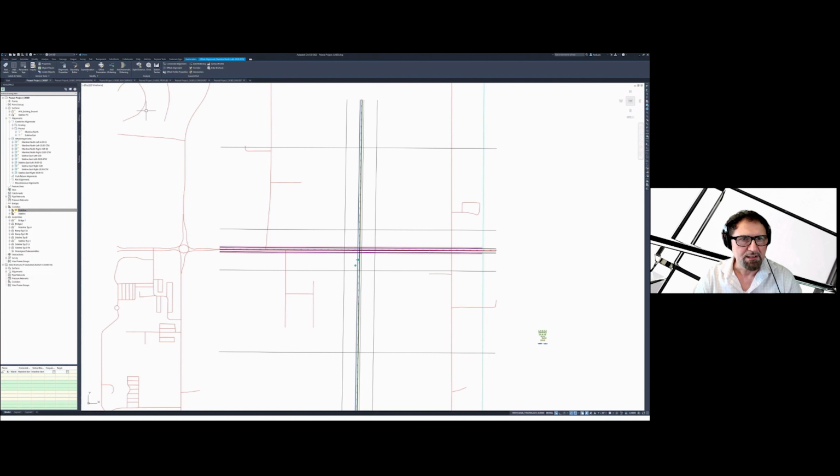line. So this is done by using the widening option, and I will not create a new alignment, rather edit the existing one. Over here, I can start from selecting that intersection where I first sketched out schematically. The station value is the same, and finish over here.